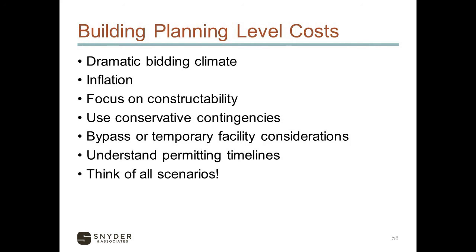And then just thinking of all scenarios, any system impacts that could result of rehab, such as odor control, more concentrated flows to the plant. Do we want to line one section at a time or smooth that out for multiple sections while we're there? Just making sure that we're not so focused on one element of the project, that we're looking at a high level overview of everything that is going to be impacted by that type of improvement.